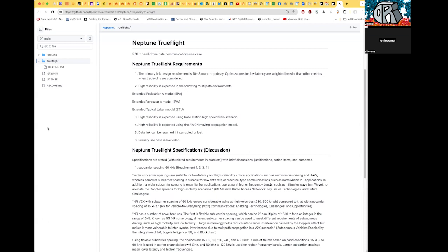So that's why I feel like it's valid to do OFDM. I don't know if theoretically it's been proved to be optimal, but it's definitely done the best job, and it's a nice, solid, understandable approach to the problem. It doesn't have some voodoo or weird little tricks or kludges to make it happen. It's basically just saying, hey, we're just gonna go where the interference isn't, with a spec that can readily adapt and move around depending on how the system environment changes. So that's why I think OFDM is valid for going forward.